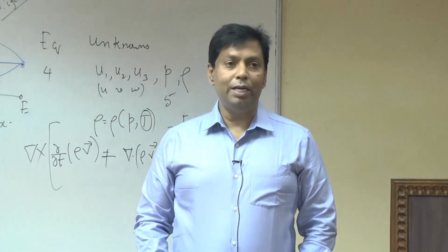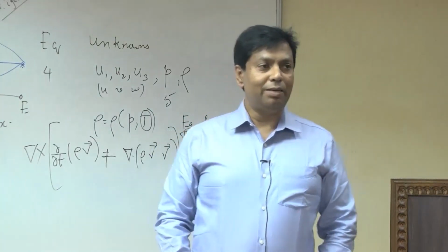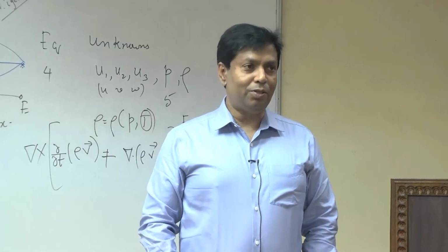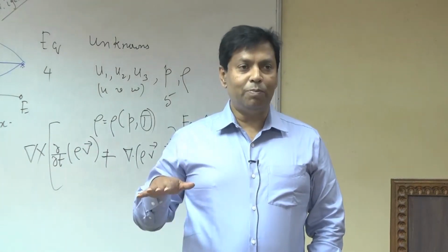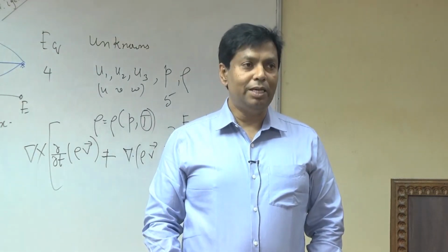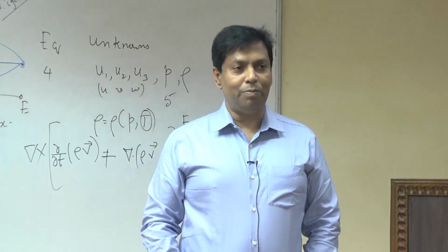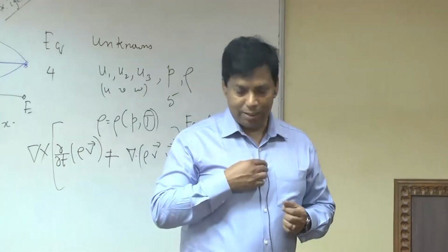But what he will do is he will use a very coarse mesh, so that we can get a very quick solution. Otherwise, it will take a long time for the solution, and then we won't get any time. So, this is only for demonstration purposes, but when you do the real simulation, you have to do the mesh dependence test. Okay. So, I think I should welcome him to start it.